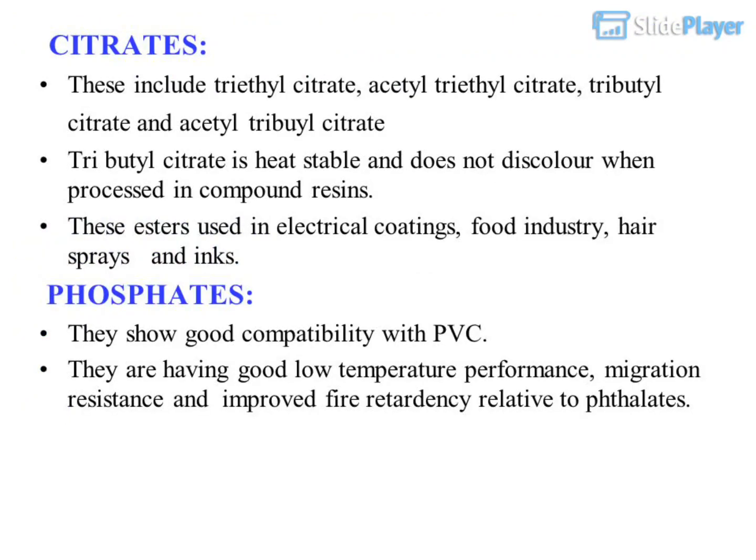Citrates, phosphates. These include triethyl citrate, acetyl triethyl citrate, tributyl citrate and acetyl tributyl citrate. Tributyl citrate is heat stable and does not discolor when processed in compound resins. These esters are used in electrical coatings, food industry, hairsprays and inks.